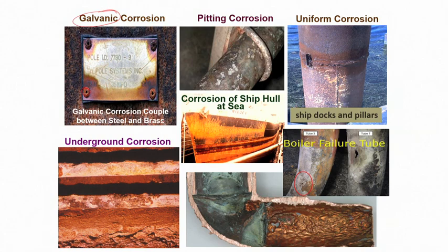a very corrosive environment in the coastal area, provide you a very nice couple, a galvanic couple, where copper or brass will be more electropositive and iron will merrily corrode, or becomes an anode, and will actually undergo very easy dissolution. So you keep losing iron and iron forms rust, and this is a complex form of hydroxide, and because of